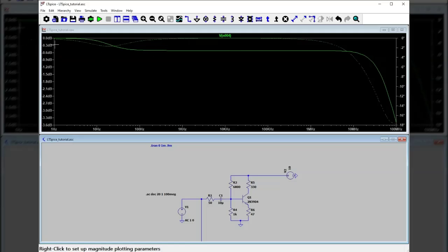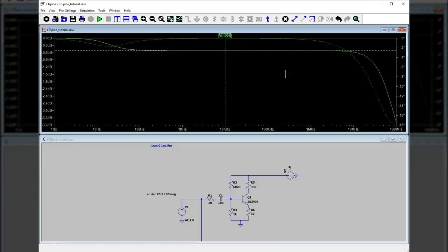Now, if you want more accurate and not have to try to figure out what this is reading off on the left axis over there, if you left-click on this, a dialog box will pop up over the right side of your screen, which you can't see, which says that at 10 kilohertz, for instance, I'm at minus 513 millidB, which means minus a half dB. So this is 0 dB here. 1 volt is 0 dBV. This is minus a half a dBV. That's something around 0.95 volt, let's say.